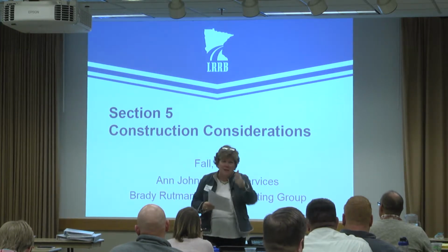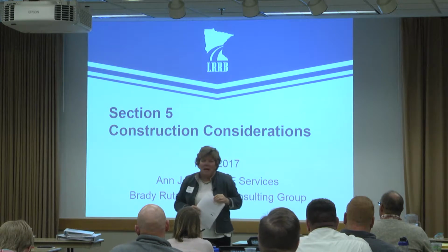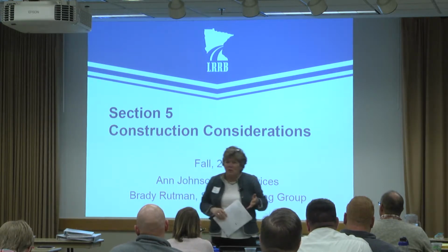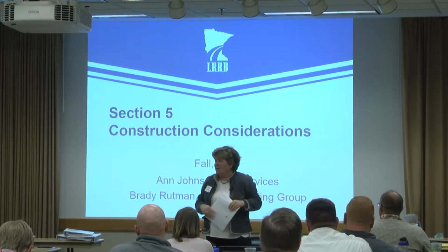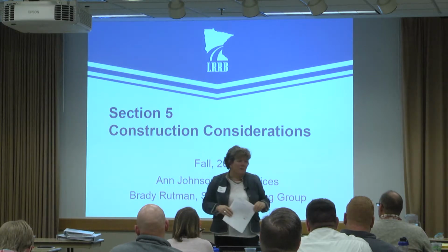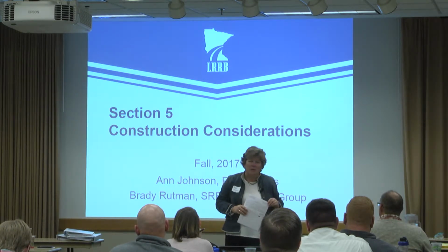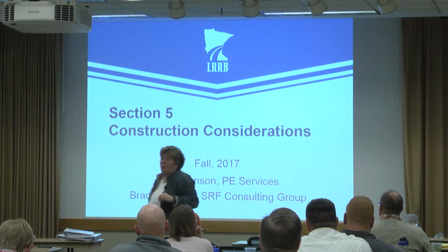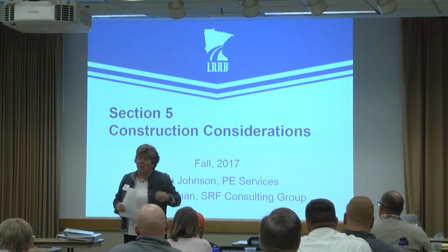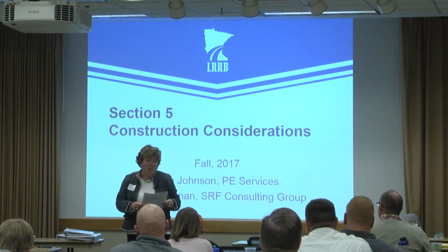Watch your jointing. I think some other people agreed with me that you think the contractor's going to joint it a certain way. You leave and go check on the next ramp, come back, and he's got it sawed some weird way. Once it's sawed, you don't have much control. So if that's an issue for you, talk to the contractor ahead of time and make sure you're on the same page.